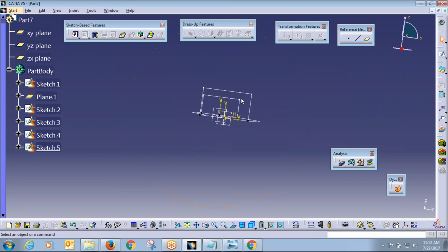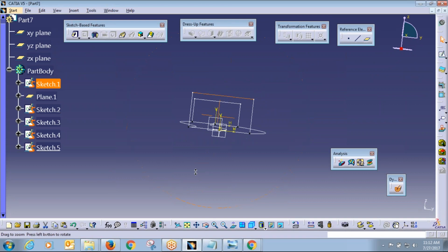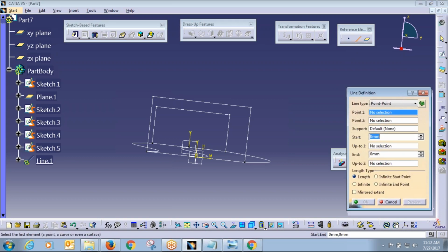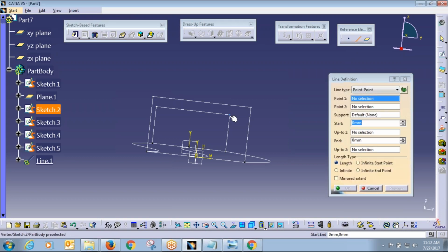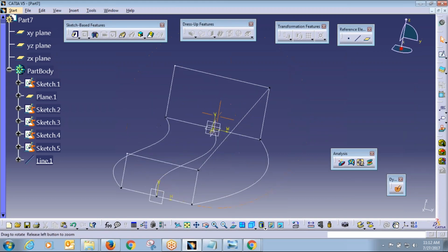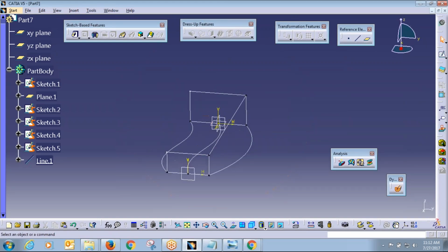Now the level over here and here is different, so I cannot use a sketch in CATIA to draw it. One thing is, I can draw some 3D spline from the surfacing workbench, or some line also we can use. So these reference elements, line point to point, say from this point to this point. So these two lines I have joined.